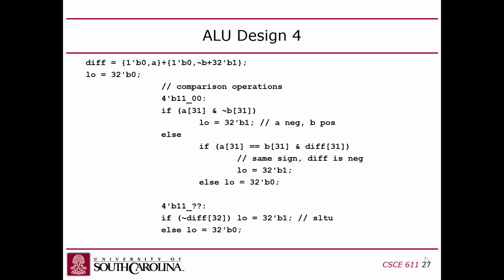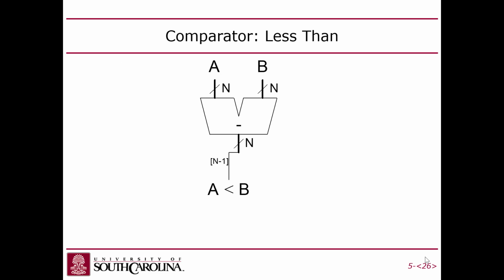So it turns out that that works, right? Makes sense? But if they're both negative and you've got A = -4 and B = -5, this would be -4 minus -5, so the result there would be 1, which would be a 0 sign bit, which means the result is positive or 0, and that should be a 0.